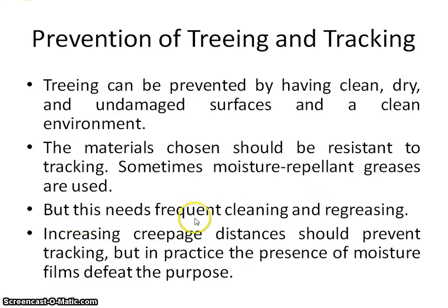But this needs frequent cleaning and regreasing is also required. So this is one precaution we have to take as regular maintenance. Increasing the creepage distance should prevent the tracking. So creepage distance should be increased to prevent tracking. But in actual practice, the presence of a moisture film defeats this purpose. Because of the moisture, we fail to prevent tracking and treeing.